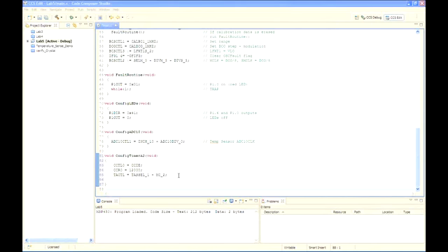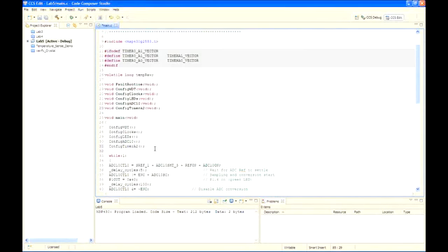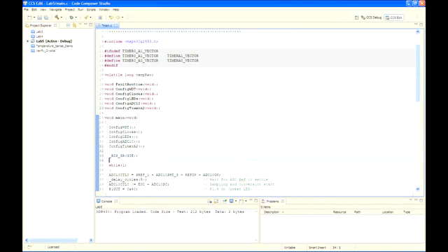In step 8, we've enabled the CCR0 interrupt, but global interrupts need to be turned on in order for the CPU to recognize that individual interrupt. Right before the while loop in main, add the following: BIS underscore SR underscore register, GIE. GIE is global interrupt enable. So now we have the timer enabled, interrupts enabled.